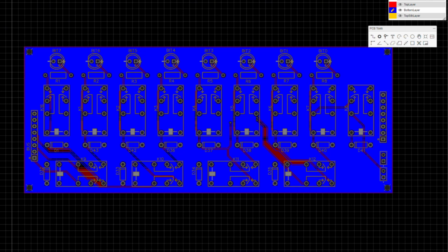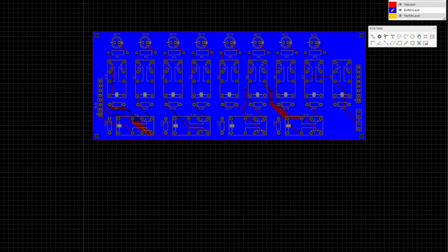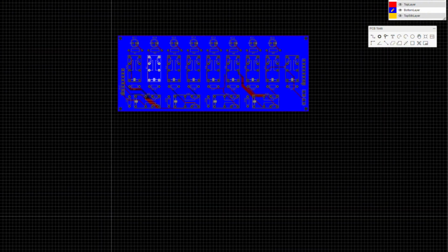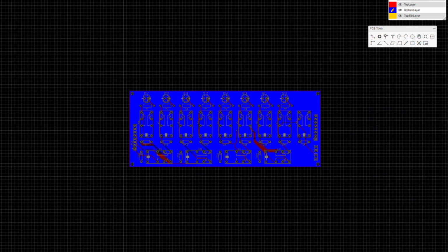Then you have this one over here. This pulls off the power in the relays, so you can read the bits without having to set. And this will go off to the ALU. And there will be 3 of these boards. So your C register, A and B registers, and then the buffer board for the ALU, the program counter and its buffer, and also the instruction register will be basically the same as this, just slightly different placements.